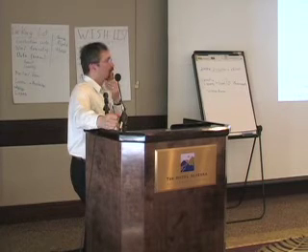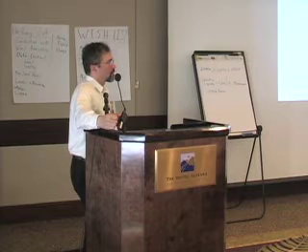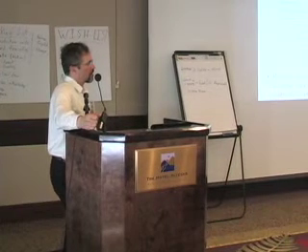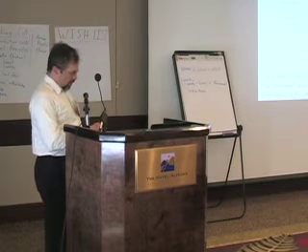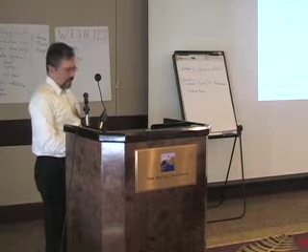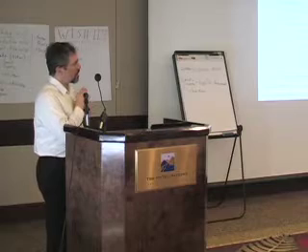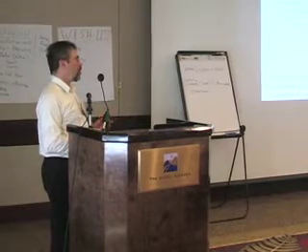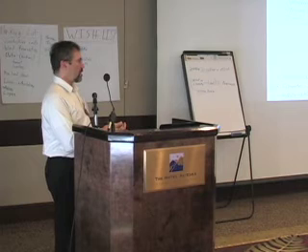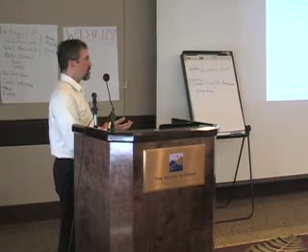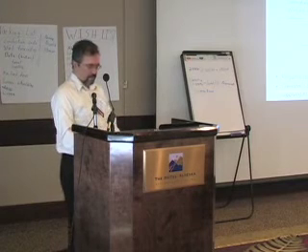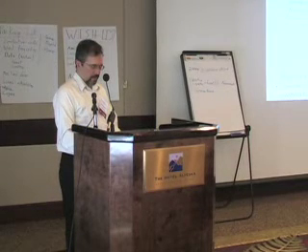So for short-term wind pulses, they may be able to be handled. So that if there was that extra capacity, then the wind power there, 50% may be appropriate rather than 100%. Right. That's an interesting point, which I hadn't really thought about. This is useful to me. It could be that we should be asking for surge capacity and using that for the spinning reserve, depending on the time duration.